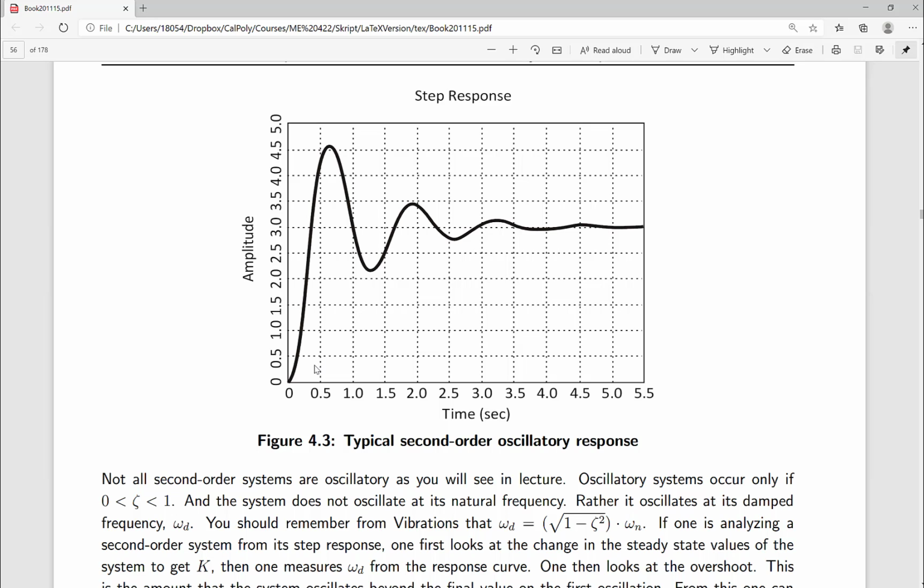You have failures because the people designing them design for one temperature and then move it to another, but fail to recognize that in going from one temperature to another, or one pressure to another, or one location to another, it may actually overshoot beyond the aim point. And if you haven't designed the system to handle that extra room or pressure or tank height, then you can have a problem. So that's the problem with second-order systems design.